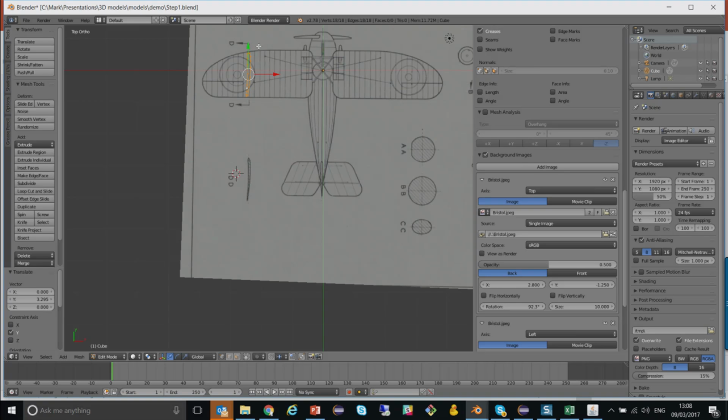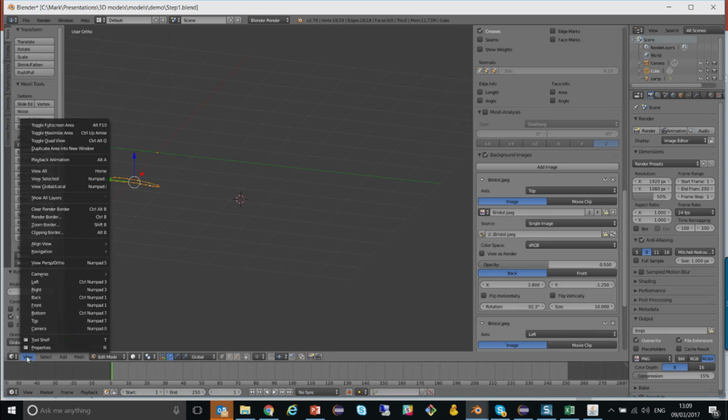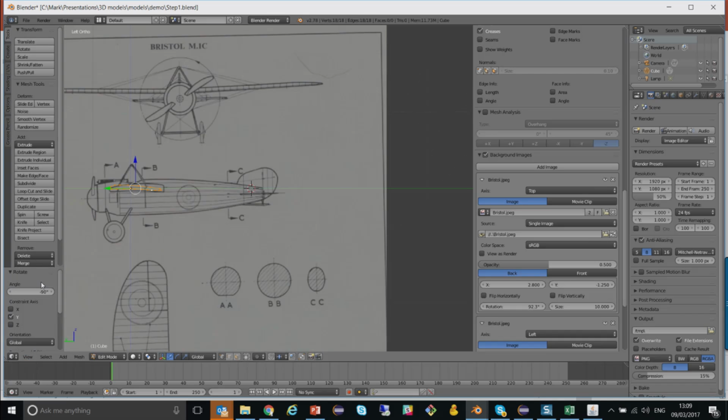So using the shortcut, I've got the section highlighted. I'm going to press R to rotate. I'm going to rotate that on the Y-axis by -90 degrees. I'm just going to accept that. Now using the middle mouse button, this is a very unconventional UI, I'm just going to tip the model up so that you can see that I'm starting to draw the cross-section of the aircraft wing here. I'm going to change the view now so that I'm looking at the left-hand side of the aircraft, and you can see it's lined up perfectly with the side of the aircraft.